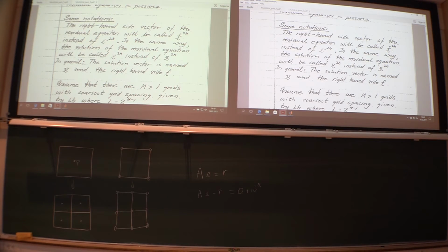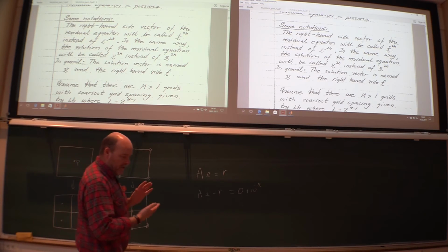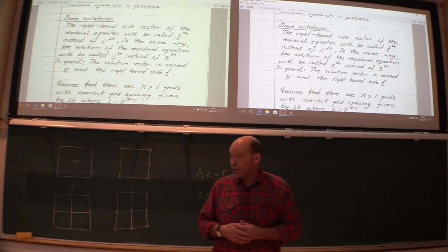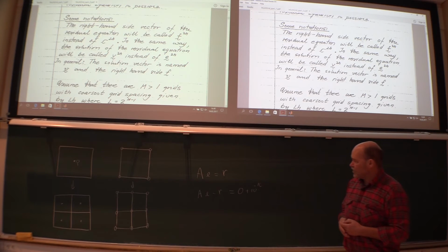Here, with the 2-level system, we solve it on the coarse mesh. You solve the equation system on the coarse mesh. Now, how to solve it? Well, why use complex, expensive direct methods when we now have multigrid available? So, of course, what we do now is extend the coarse grid correction with many grid systems. So, from the coarse mesh, you go to an even coarser mesh.